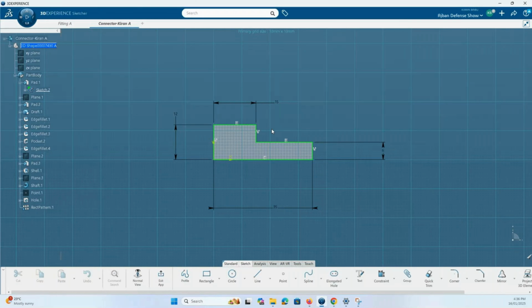The rule of thumb is base body: you create the base body and then start adding features to it. The idea is always to build up the exterior part of the part and then start building the internal structures, like the way you can see how I did it. When you talk about constraining the part, the idea is to go cyclic, so either clockwise or anti-clockwise. I have a habit of going clockwise.